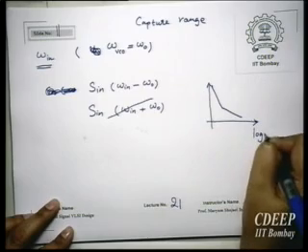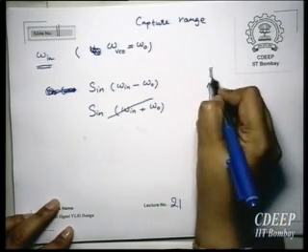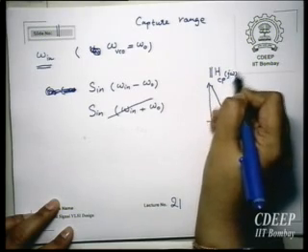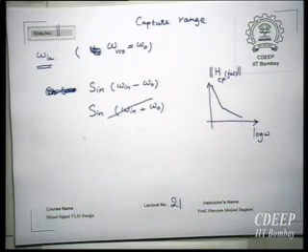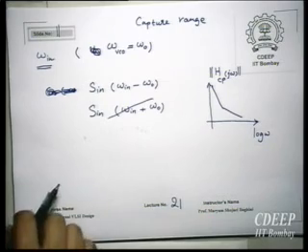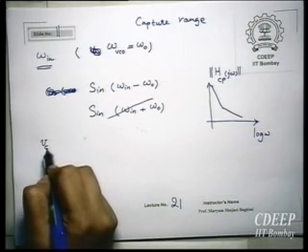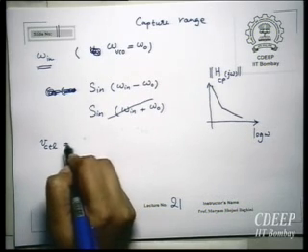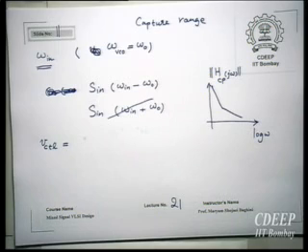Log omega. This is the magnitude of H of the charge pump. So it's something like that, and therefore it will start attenuating. Whatever transfer function it has, after all, what I will get at the output of this, which will in fact now be this VCTL, will depend on what I am getting from that effective low pass filter.